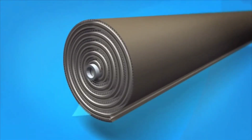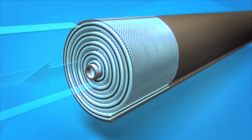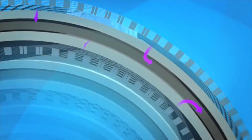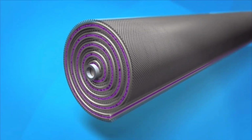Feed water is forced through the feed channel spacer and into the barrier layer of the membrane. Water passes through the membrane surface into the permeate channel. It flows in a spiral direction and collects into the core tube. This water is the final recycled water product.